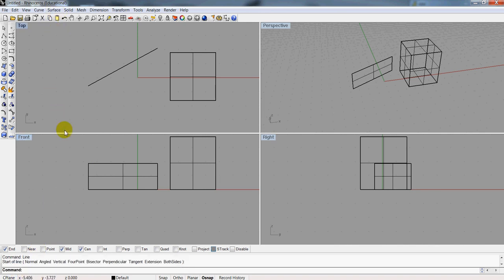And the other thing that's nice is that if I hit L, then I get all the commands that start with L. I hit I, now I'm refining my search, N, refining it even more, E, and there's still some more. And you can actually just go down here and click on them and say line through point. And so then you'd select 2 points and you'd get a line through those 2 points. So that's using the command line, and I'm going to do a lot of that in this. And I think that it's a pretty useful and quick way of entering commands and working in Rhino. So I'd recommend that you familiarize yourself more with the useful commands that you use often than you do with the menu systems, although menu systems can be a good place to start.